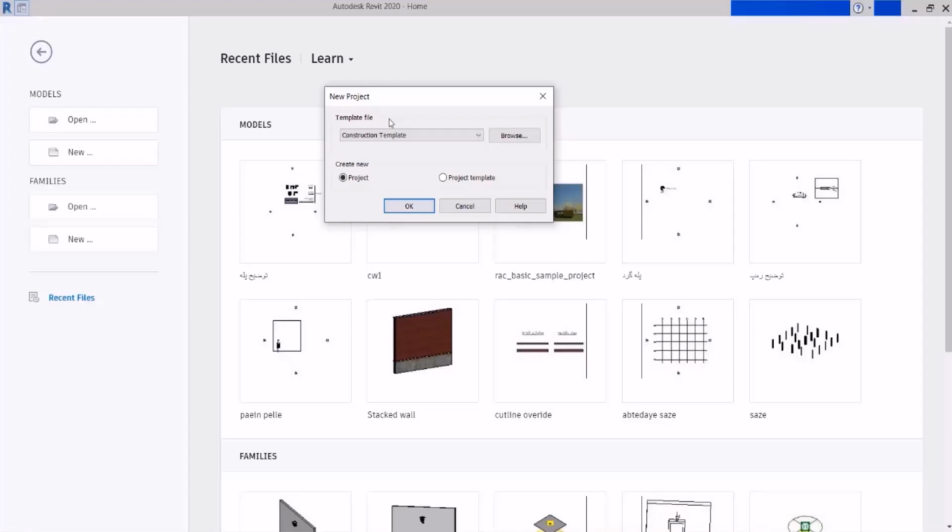And if I open this file, you see that each major has its own template: architectural, structural, and mechanical. Each of them has its own template. We can say that if you don't have this template, you can't start your work in Revit. So if you press on new and you see there's no template for you on this page, you have to add those templates in the way I explained to you before. And you, as an architect, will press on the architectural template, and then by pressing OK, you will start a new project. I won't open it now.